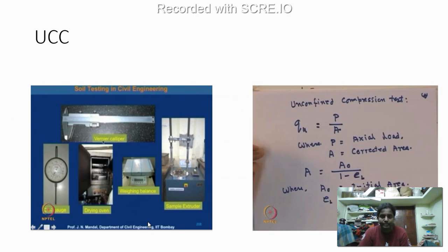So your direct shear test is a quick test again. It is an easy test to do, and it will give you the phi value directly. And for clay soil also we can perform the test. We have to give some drainage plates, and you have to conduct the test with the escaping of pore water pressure and everything. Generally, it is conducted for undrained, so cohesionless soil.